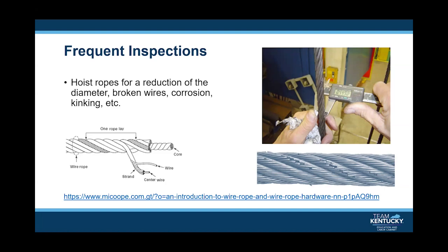That is actually derived from a newer edition of ASME B30.2. It is also included in ASME B30.16 and thereby is to be followed for cranes that are typically not covered under 1910.179. This measurement is typically taken using a machinist caliper or a micrometer and is measured from the highest points, or crowns, on both sides of the rope.